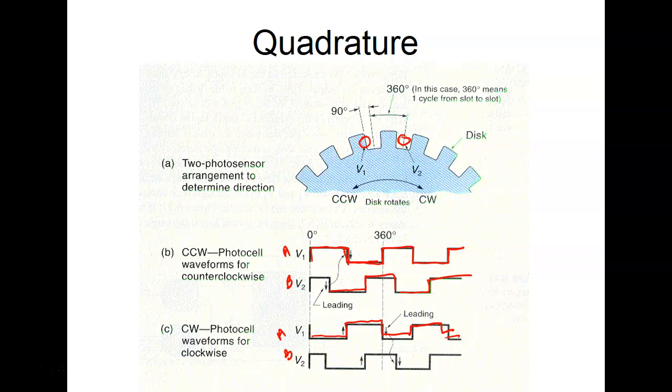Well, that depends. The Fanuc robots use regular alkaline batteries, so it's very cheap to go out and change the batteries on the robot because it's no big deal. A couple of the big Fanucs have 4 D batteries, and the small Fanucs use 4 C size batteries, just regular alkaline batteries.